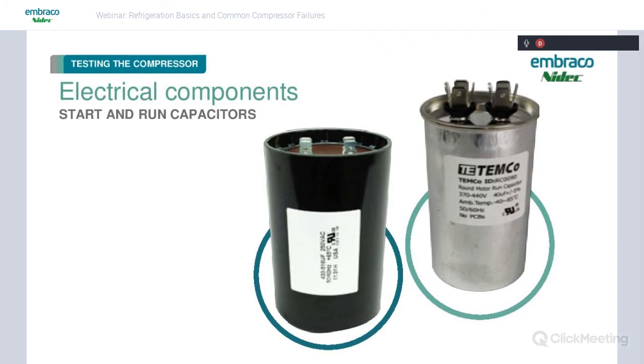And you can check these. The best way to check these is with capacitance on your multimeter. And just make sure that they at least get up to the microfarad range that's stated on the shell, and they should be good. Now they do wear, so you do want to check these. They do wear over time and may not be able to get into the correct microfarad range. So it's important to go ahead and check those whenever you can.